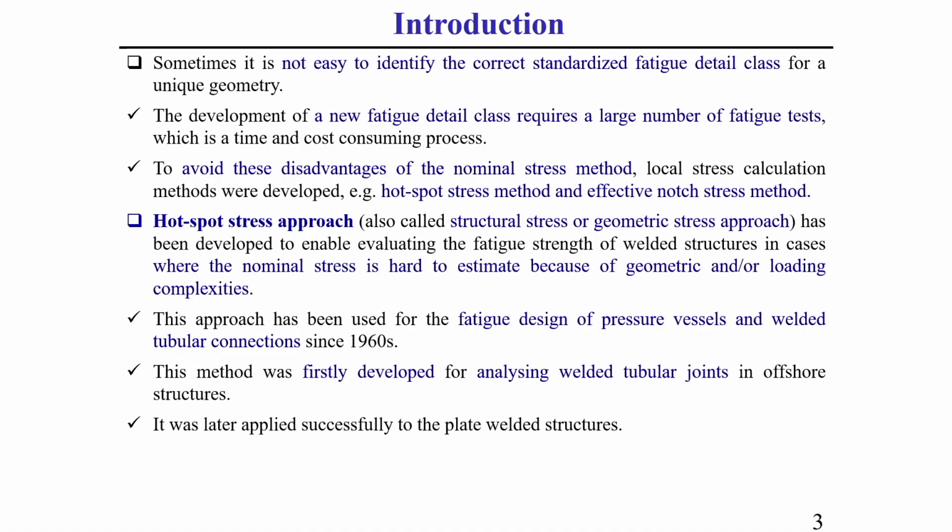But sometimes it is not easy to identify the correct standardized fatigue detail class for some unique geometry. The development of a new fatigue detail class requires a large number of fatigue tests, which is a time consuming and very costly process.